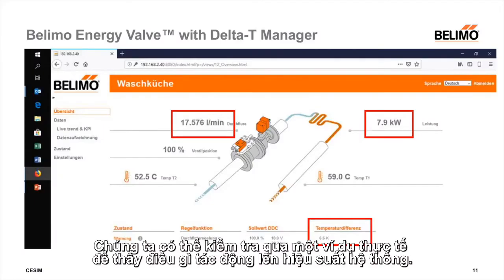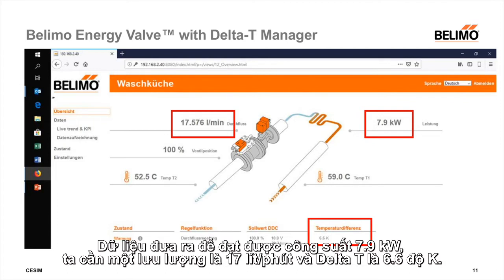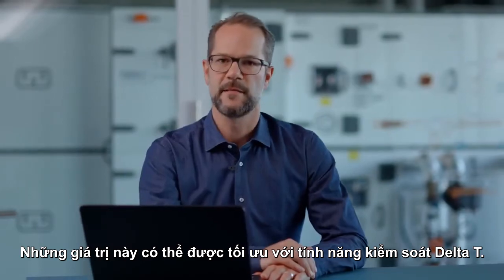We can see from a practical example what such an increase in energy efficiency really means. Here we can see the data of an installed energy valve with a condensing boiler. The installation data show an output of 7.9 kilowatt, which is achieved with a flow rate of 17 liters per minute and a differential temperature of 6.6 Kelvin. These values can be massively improved with the delta T manager, as we can see here on the next slide.